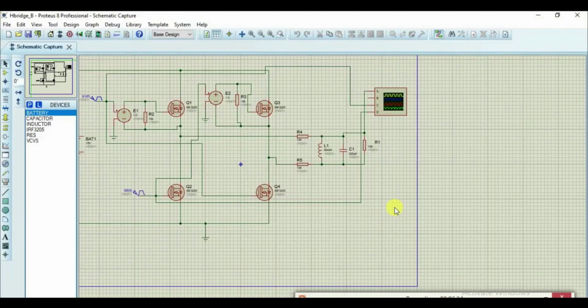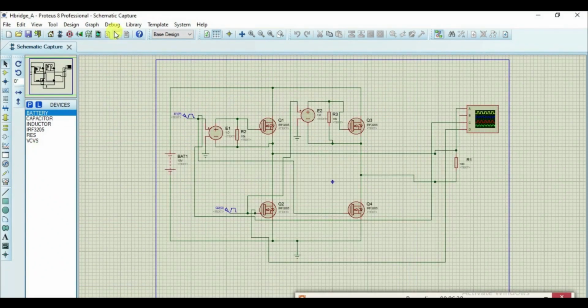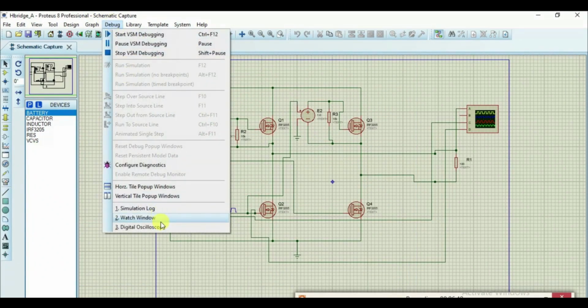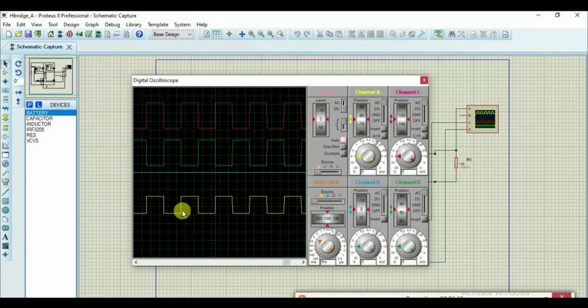I think you all know that, let's see this section. See, without the filter, what were we supposed to get? We were supposed to get a pulse wave. So if you have the knowledge of Fourier series, you know that in a square pulse we do not get even harmonics, we only get odd harmonics.